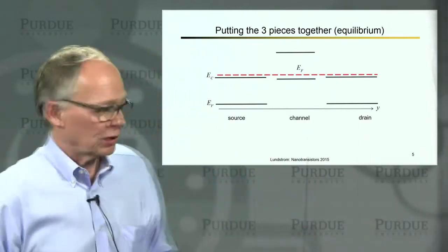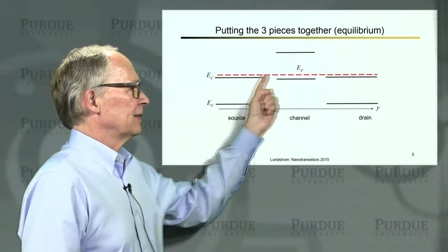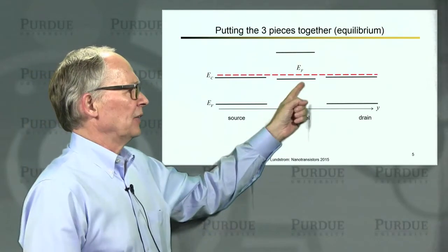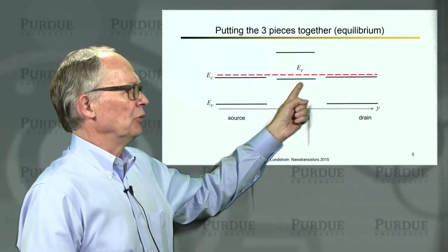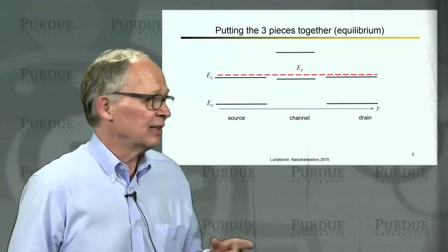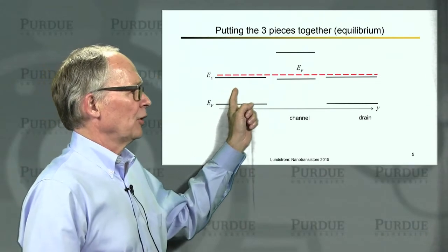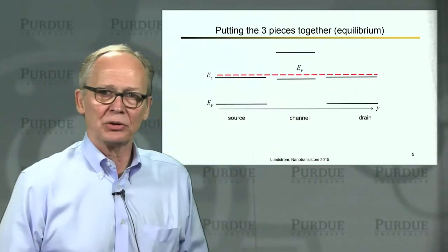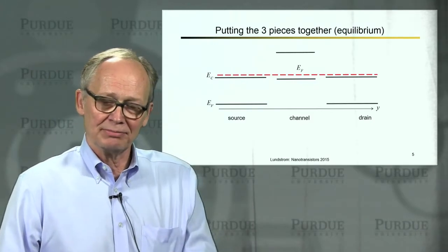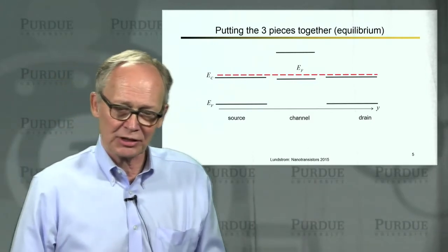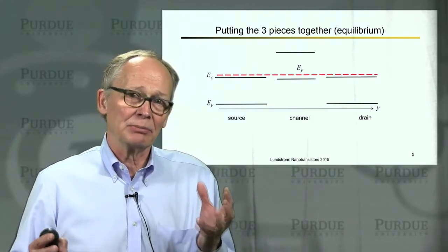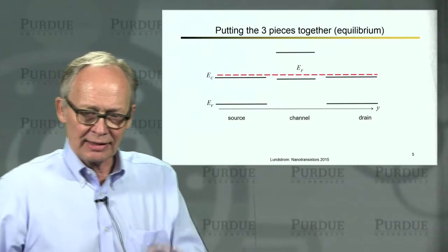So this is how it would work. So here we have the constant Fermi level. We know things have to end up that way. If I assume that I've grounded the p-type layer, so its potential hasn't changed, you know, all potentials are relative, then it means that I must have developed a positive potential on the source and the drain, because positive potential lowers electron energy. That's one of the things we learn in freshman physics usually. So we have developed a positive potential. We would call that a built-in potential in semiconductor theory that has lowered everything.